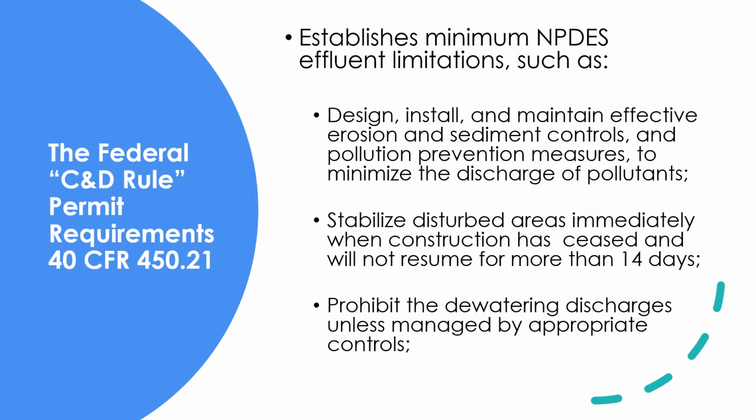And you also want to stabilize any disturbed areas immediately when construction has ceased. This is a big one when I was going out and doing inspections. That was an issue, because if you know that you're not going to be working in an area of exposed soil or sediment for more than 14 days, you're legally required to cover it. A lot of times this can just be a tarp if you're going to get to it really quickly. If you're done with that area of a construction site, you should grass it and stabilize it so that that's not an issue any longer.